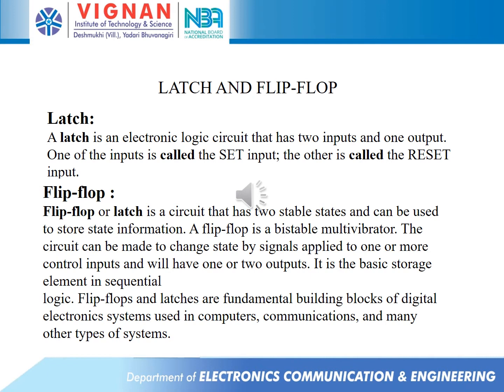And a flip-flop. A flip-flop is the same in functionality as the latch, but the way it operates is different. The difference between a latch and a flip-flop is the way they are triggered. A latch is triggered by the level triggering process and a flip-flop is triggered by the edge triggering process. For triggering purposes, we use an external clock.